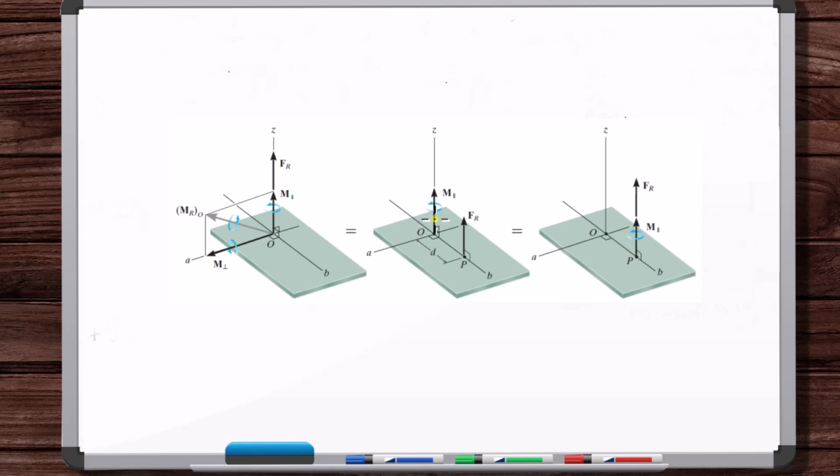But again, with simplifying these force systems, we're reducing it down to couple moments at points, couples. So these are free vectors. We can just move that couple moment vector to the point that the force vector is at. And you get this force vector in line with this couple moment vector, and that's what's called the wrench. I'm not sure why they call it a wrench. To me it's more like a screw, because with a screw, you're applying a torque, a couple, and also there's a linear force in that same direction. But it's called a wrench, and that's it.